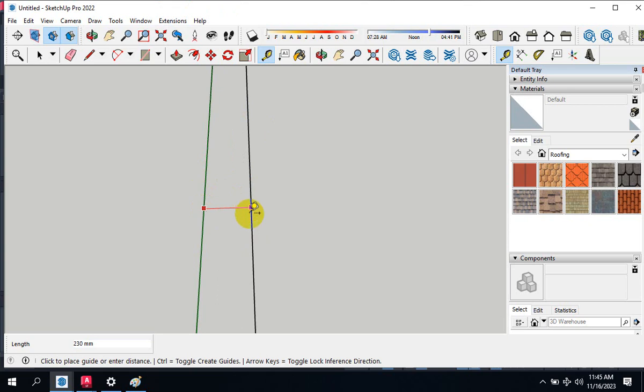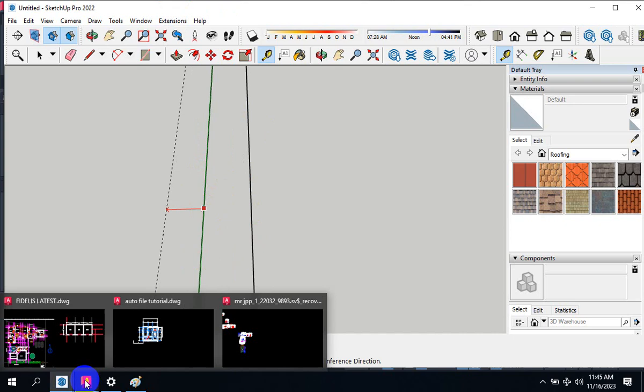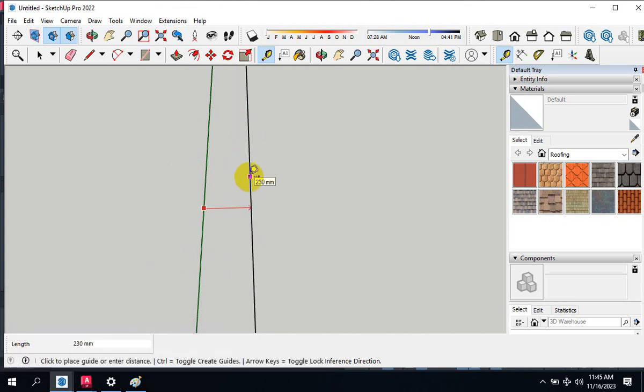Then we went back to AutoCAD, and you will see the size of the block there is also 230. So I always use a block to be able to rescale my drawing back to the actual size of the building. There are times that if you are lucky, when importing it maintains the scale, but in most cases you have to come back and rescale it like this.